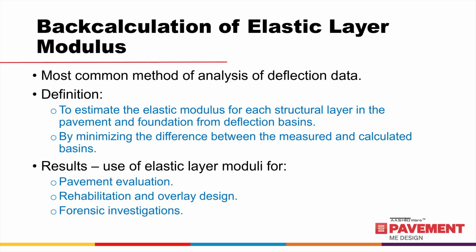Deflection basins and back-calculated elastic layer moduli are used for 3 major areas. First is pavement evaluation. Second is rehabilitation and overlay design, which is the focus of this training course in support of the PMed software. And finally, forensic investigations.